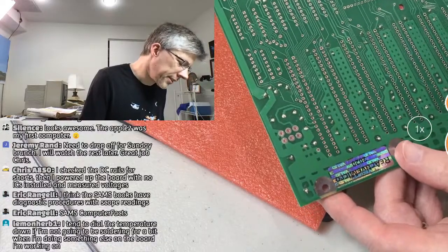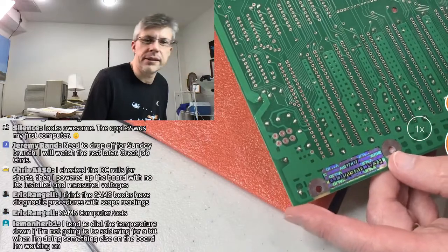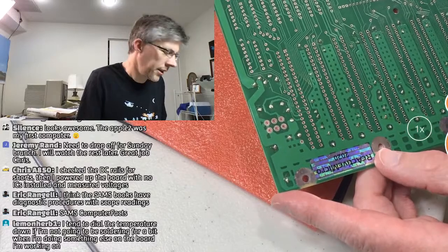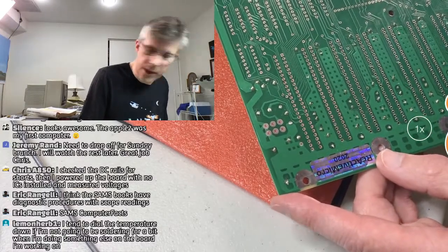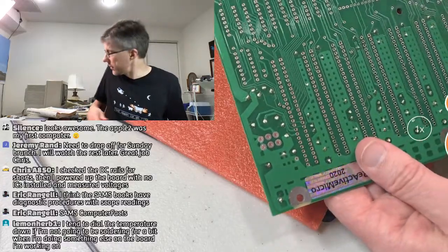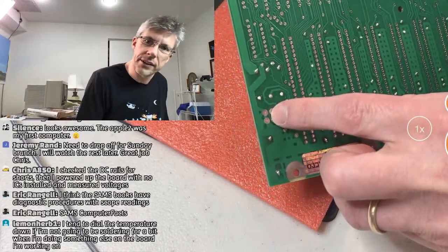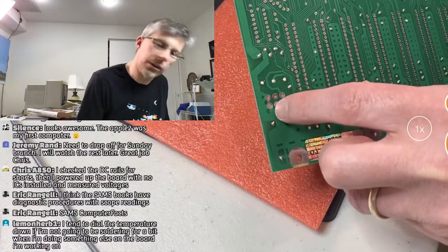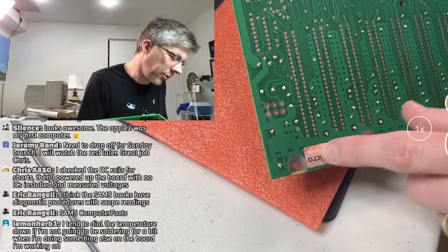These boards have rails that carry either the ground, so it's called the ground plane, or else the plus 5 volt line, etc. So for example, on this connector here, let me get my cheat sheet. These are the ground lines here, and you can see this faint lighter outline. That actually is carrying the ground all the way around the board.